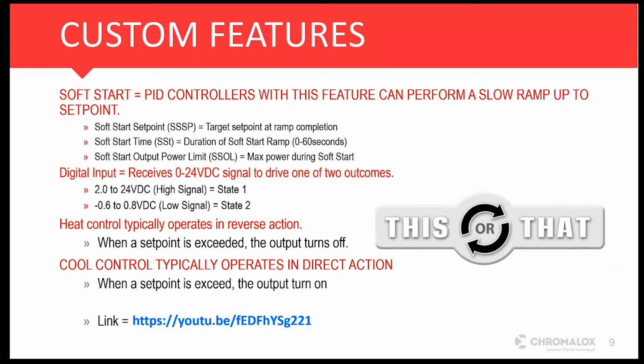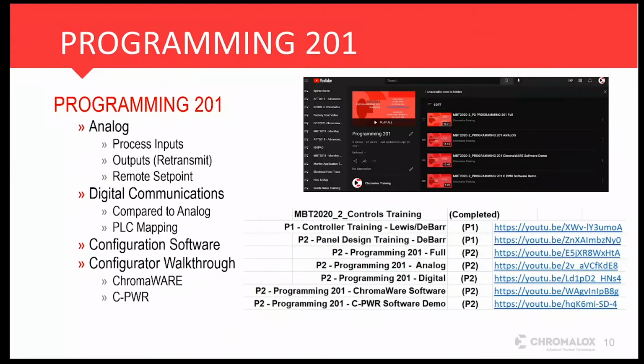There are other settings in there. I call them gotchas a lot of times. Think of reverse acting versus direct acting. Well, what do those terms mean? Actually, with reverse acting, you've got to think of it as your heating cycle. You're heating up, as opposed to direct acting, which would be more of a cooling cycle. Vince will touch on that and explain that a little further in a minute.